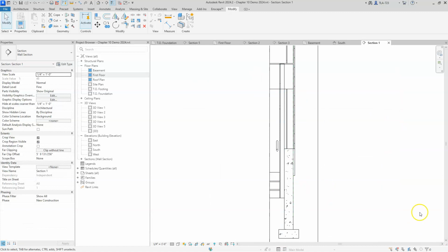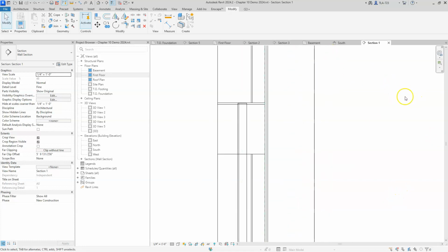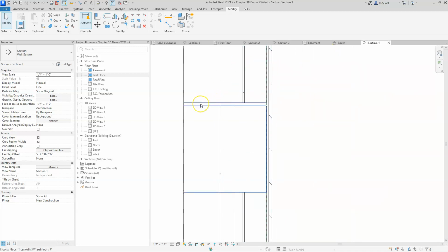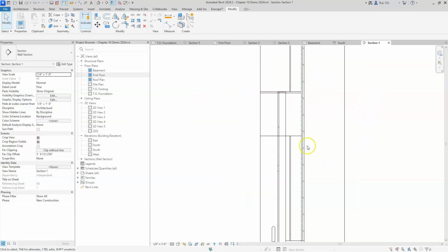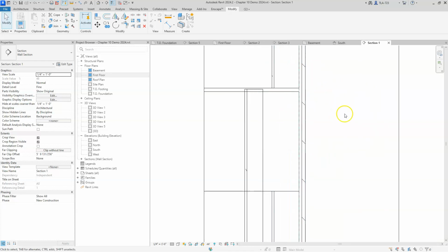So this gets a little bit confusing because we're on the back side and this foundation wall is stepped in the back. This is on a sloping lot, so we'll just kind of have to parse through what's going on here. But you can see right away that the floor actually did carve the geometry out of this wall, which is what we wanted. We don't have to contend with a mud sill down here or anything. So this is exactly what this should look like.